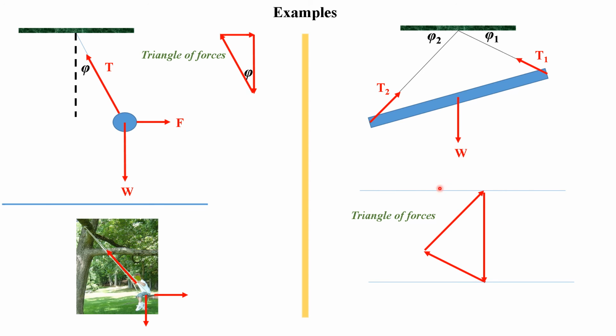So we can draw two lines horizontally here, and then using some simple geometry, if this angle is theta 2, then this is 90 minus theta 2, which is exactly that angle. And the same thing here can be produced from here, from some simple geometry. And once you have those angles, you can apply the sine rule to work out those forces. So if the weight is known, and if theta 1 and theta 2 are known, you can easily calculate the tensions in those two strings using the sine rule.